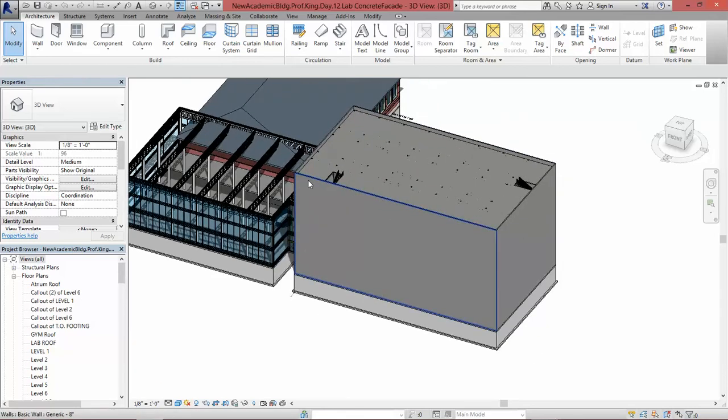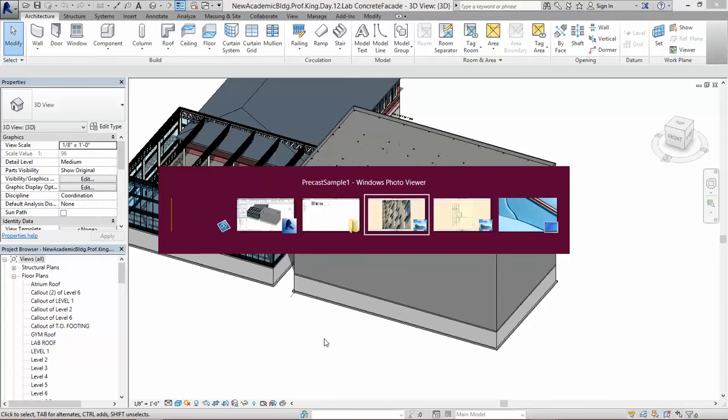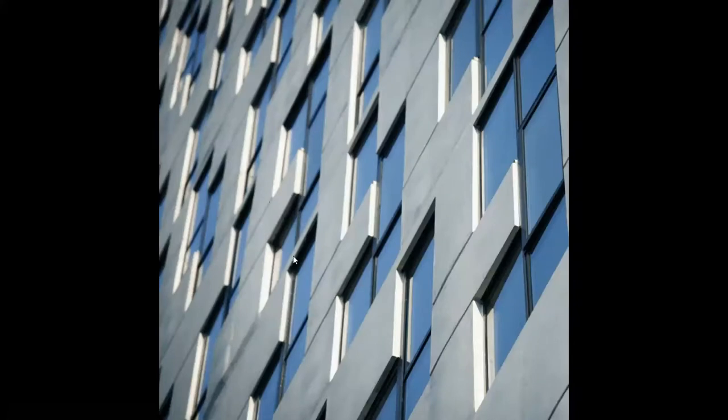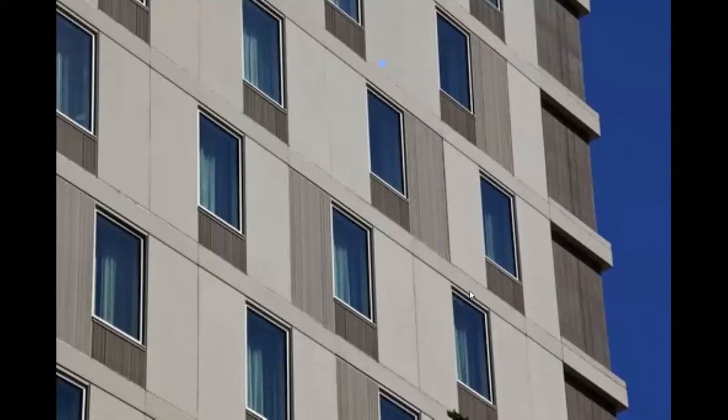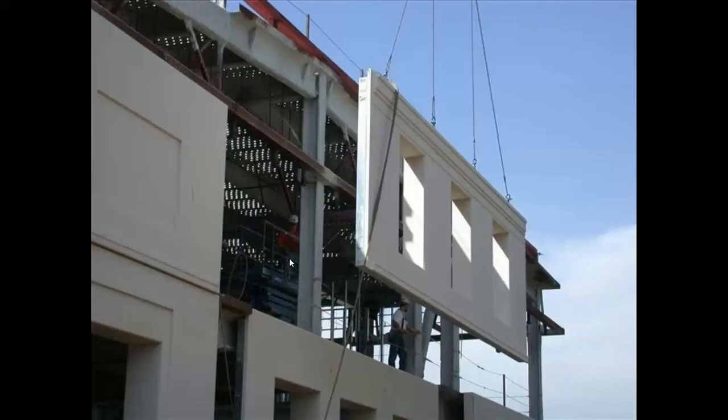So I'm going to make this facade with the precast concrete elements, and just explain the process. Precast, as you know, is just elements that are isolated. You can mount them one by one, singularly, as components. You can see these images. You prefab this in a different place, and you locate them directly to where they have been thought to be placed.